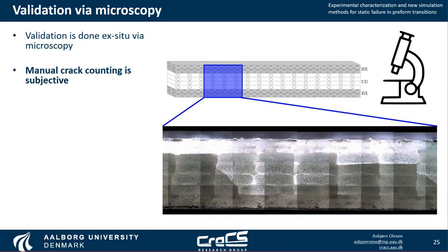So we need to define what is actually a crack here. What we did was take the cracks that we expect, which are working normal to the direction of tension, marked here in red, but we also have cracks that are occurring out of this plane, marked here in green. These are also counted as cracks, but as new cracks.